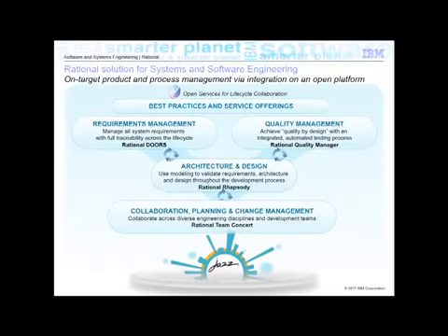In summary, this demonstration showed how we can manage an ISO 26262 project by showing the use of and collaboration between Rational Rhapsody, Rational Doors and Rational Team Concert, as we took a set of system requirements, developed an item definition, carried out a failure analysis to determine the ASILs, safety goals and safety requirements, and from this a functional safety concept. We ended up with a physical architecture.